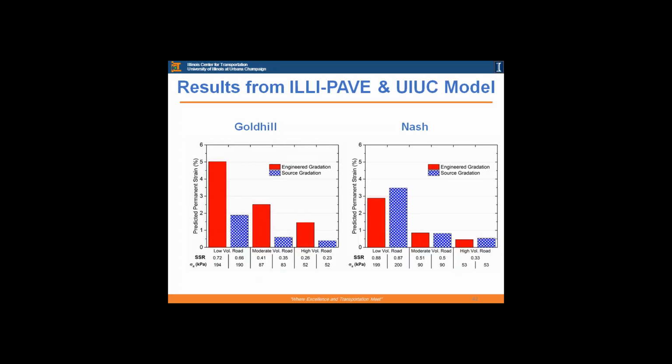And if you look at some of the user material models in Abaqus and other general purpose finite element programs, those material models are all, with Jacobians and things, a function of strain state, not stress state. That's because, again, it comes from the old geotech idea of making modulus a function of strain.